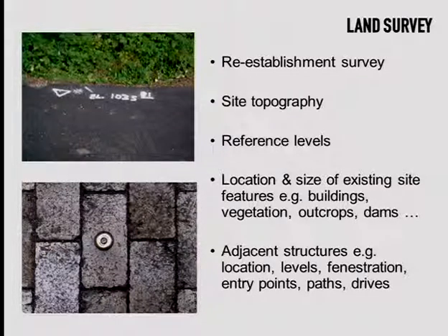So if you see one of these, this is a reference level back to an official level as to what sea level is in Victoria, which is an average tidal change height, which is averaged out, and that's given as a reference, and then all official heights are given to this AHD back to that reference point. So it's X metres above sea level.